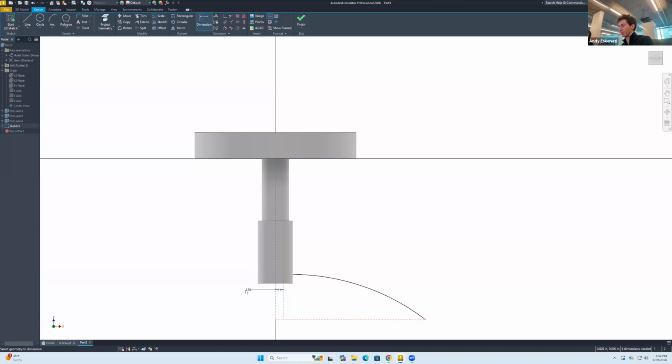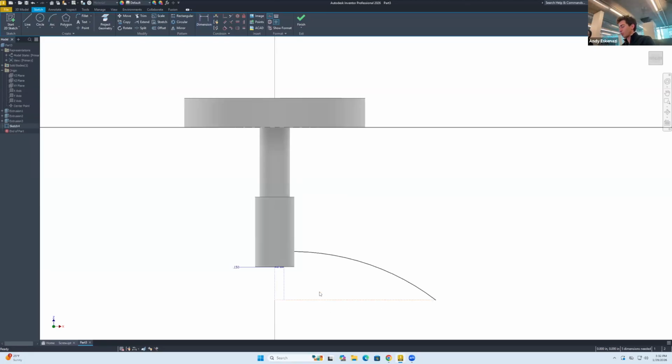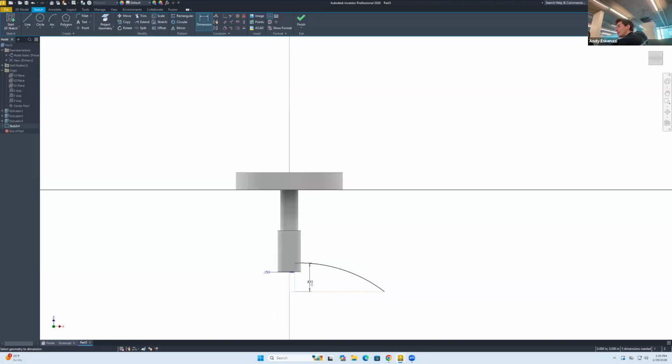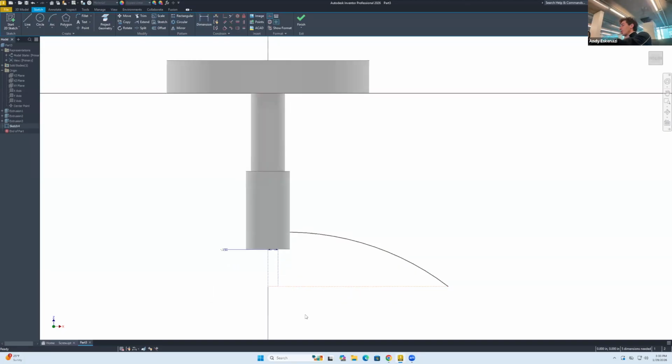This will make sense in just a moment. Let's make that 0.15. Here, the problem is that this is where you have to be extra cautious about defining all of your dimensions. So if that's 0.5, that's 3.3 height, that's 0.3 height, this means that we could technically make the distance between here and like there also 0.3 height, and then leave for the wheels 0.1 height. Does that make sense? There, that way it all scales parametrically.